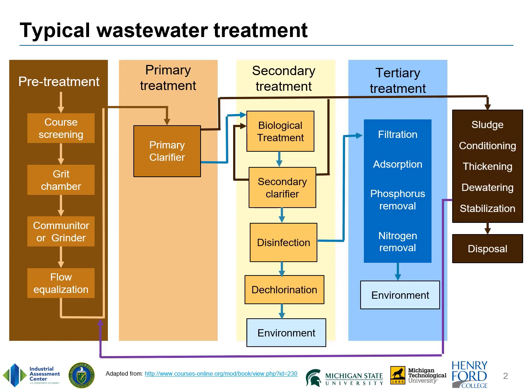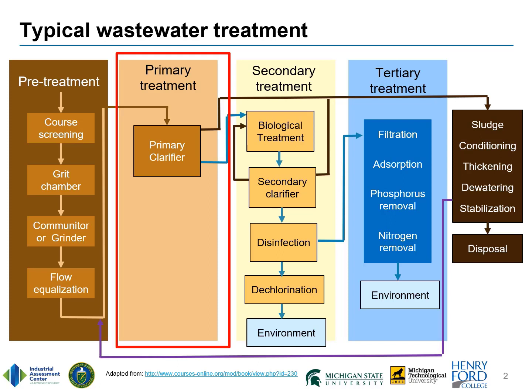We typically divide wastewater treatment into 4 steps: pre-treatment, primary treatment, secondary treatment, and tertiary or advanced treatment. Pre-treatment removes the larger material: sticks, kids' toys flushed down the toilet, wipes that shouldn't have been disposed of in the toilet, grit, sand, and other large material. It also includes flow equalization, which is used to equalize both the flow rate and strength of the wastewater.